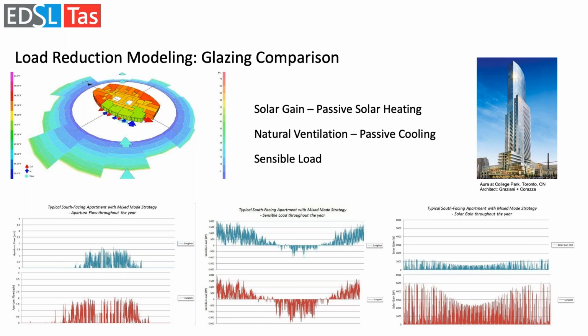You can basically see the solar gain through the year hourly, and you can see one glass is controlling the solar very much, the other one's letting a ton in, and that impact is, yes, the cooling goes up in the summer, the heating goes down in the winter, and then the central one is the sensible load. So heating's above the zero, and cooling is below zero. You can see there's a much larger cooling amount from the higher solar gain.